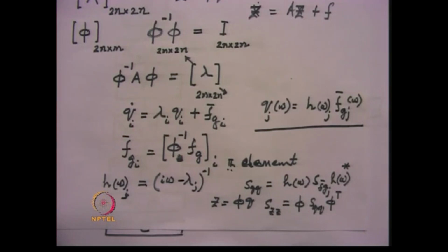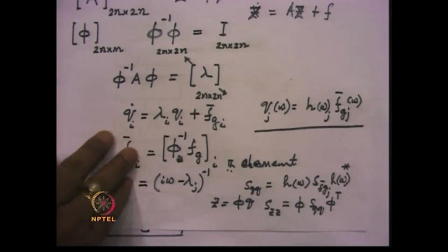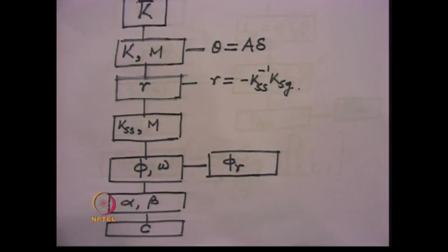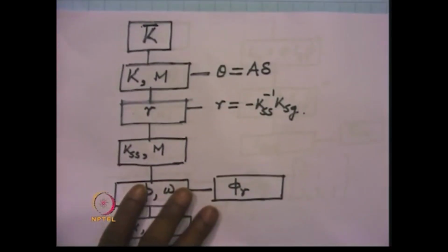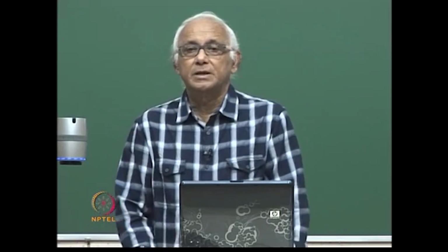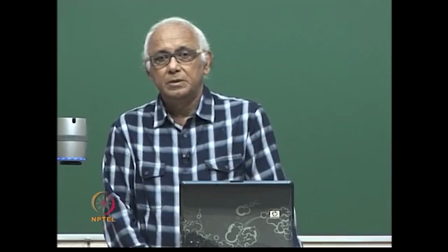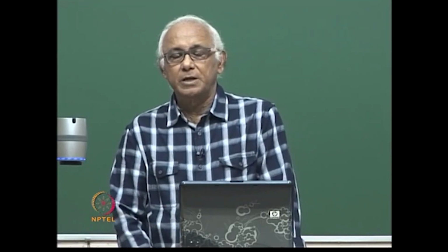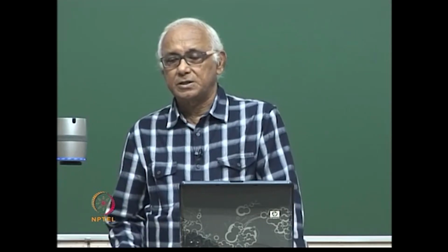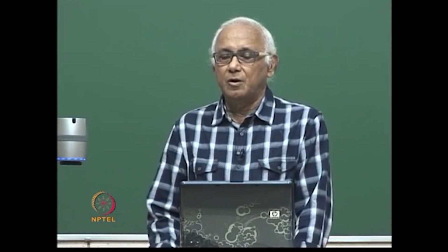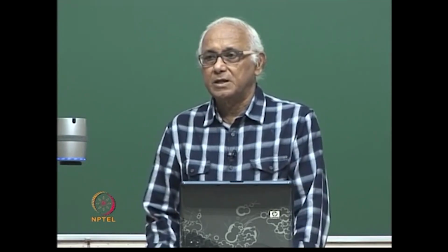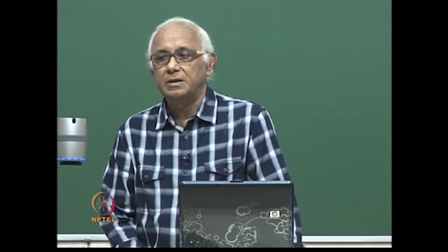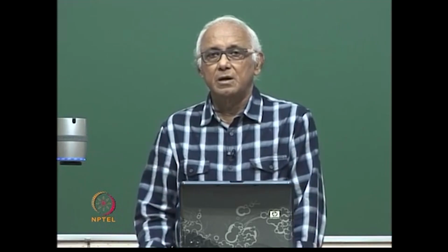So, that is how one can also obtain a modal spectral analysis using the state space formulation. Now, we have seen that there are many ways that we can perform the spectral analysis, and this spectral analysis can be obtained for a single support excitation and multi support excitation by carefully obtaining the power spectral density function matrix of the excitations. Whenever we have the multi support excitation case, then the coherence function must be defined.